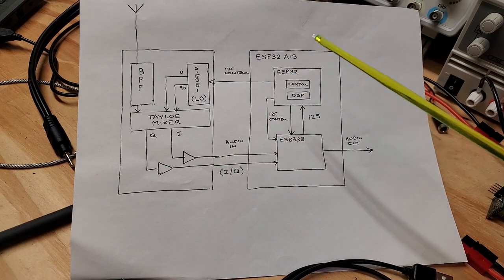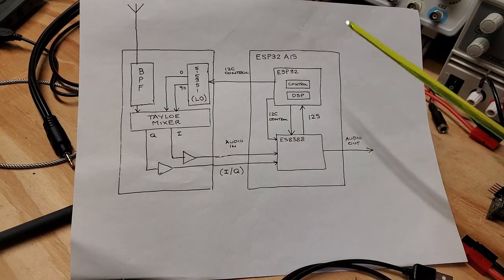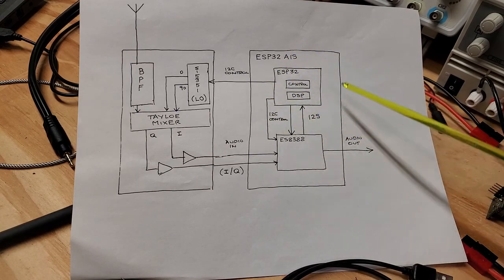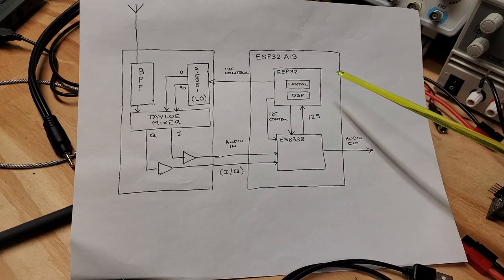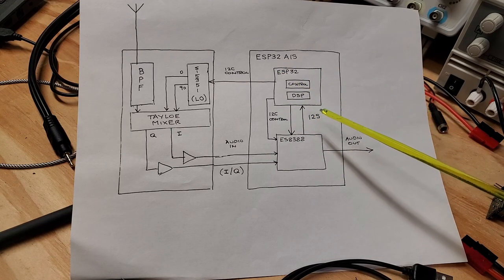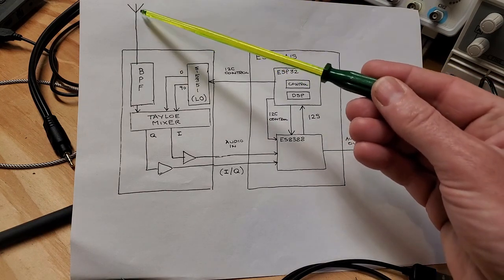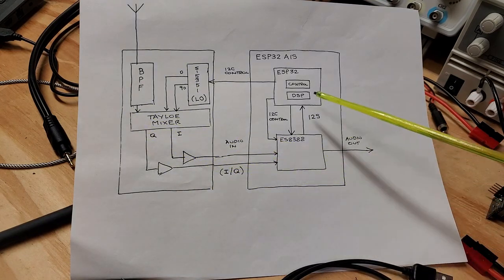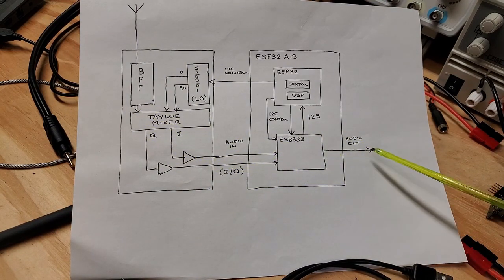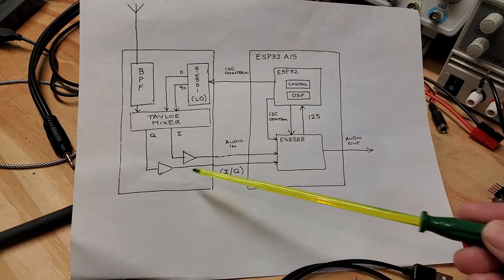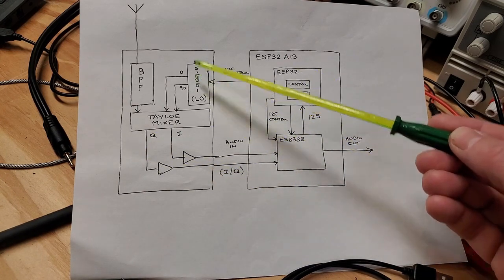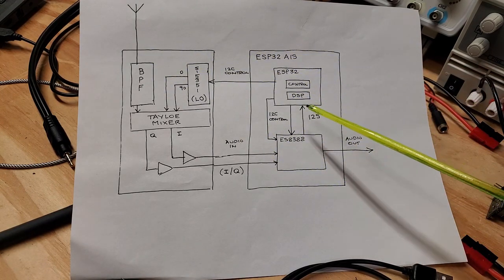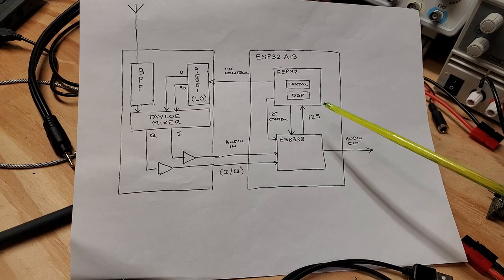We'll then move on to creating a 90 degree phase shift, and I've done this before using the Arduino audio tools, and we'll show how that can produce the 0 and 90 degree phase shift for two audio signals. What we'll then do is inject an RF signal into here, and we'll confirm that we get the appropriate audio output coming out here. And that will be at the difference frequency between the LO and whatever the received RF is here. And further, we should be able to control which sideband we want to receive.